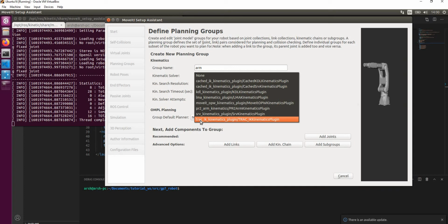The difference between FastIK and all these other libraries is that FastIK uses algebraic equations. For the inverse kinematic solution, it finds it algebraically instead of numerically. Once you have the equations, it's very easy to just substitute the joint values and get the pose, or the XYZ value, of the end effector or the tool. TRAC-IK is sort of an amalgamation of two KDL-like solvers. One is the KDL library and there is another one. So it's much faster than FastIK and KDL.